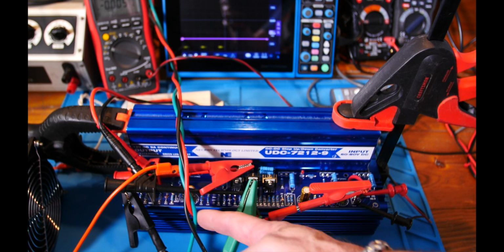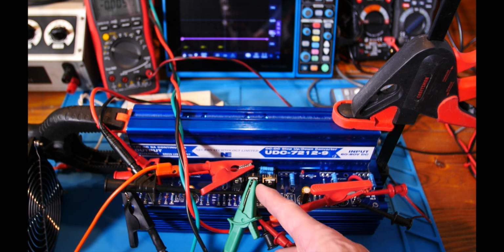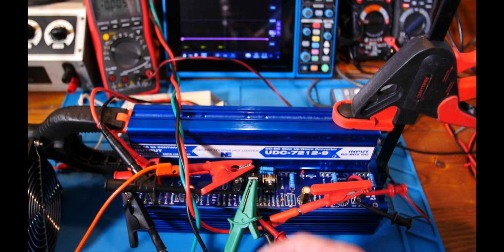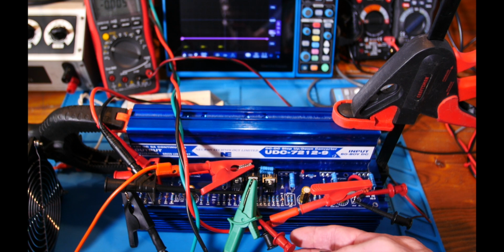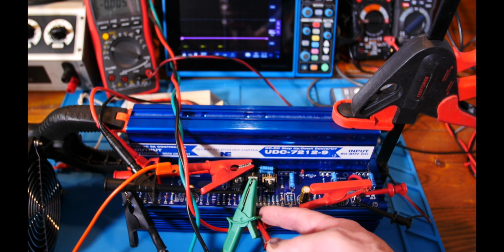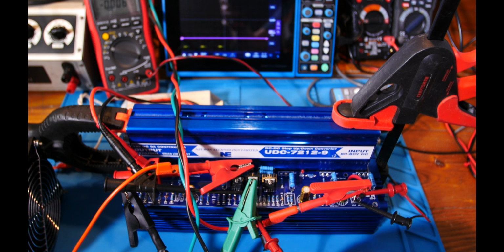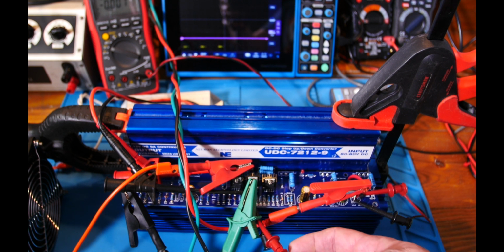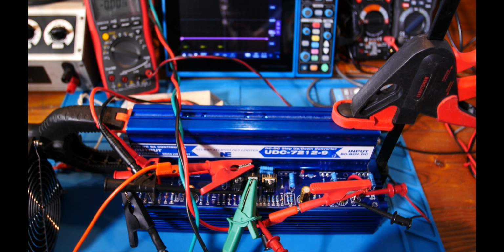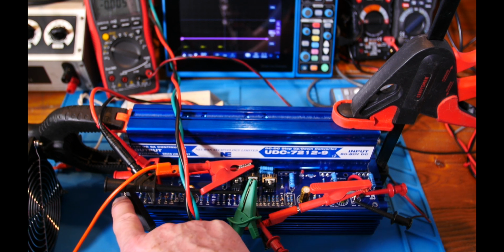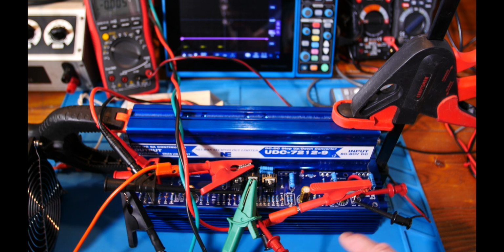And here's our power supply. The ground is coming into this ground connection I have. The generator is coming into the input terminal, which is right underneath, and its ground is also referenced there. So that is referenced to chassis ground at that point, earth ground, because of the generator. Then the black power lead goes to the black power input, and the red power lead goes to the red power input.